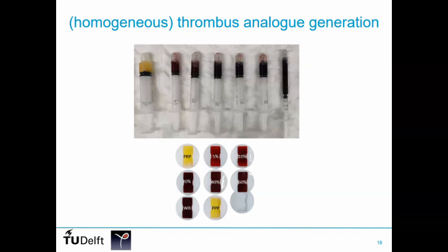The big trick here is that clamping these soft tissues is always very difficult. So we add a bit of Velcro inside the mold so that it entangles with the specimen, so that we can clamp it and pull on it. And this is how they look.